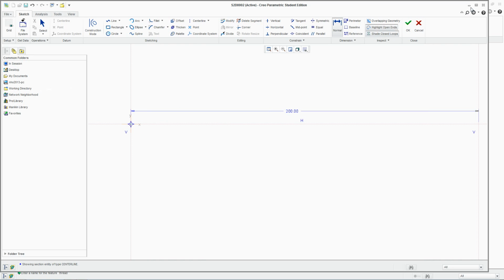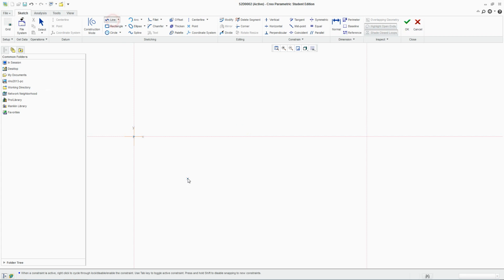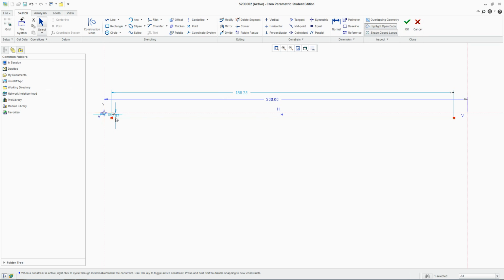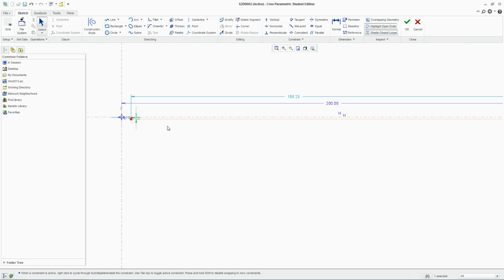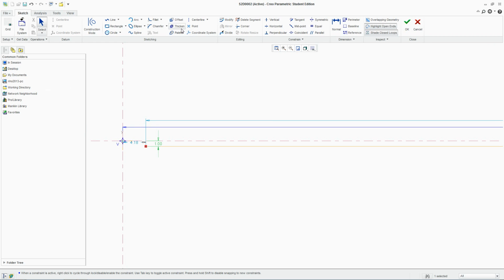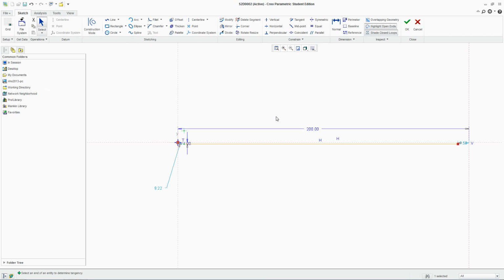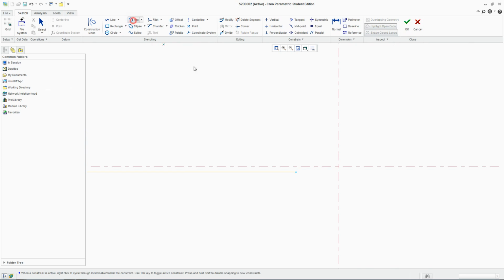Alright, so the tricky bit here, we're gonna draw a line. The cross section will sweep along without any changes until later on at the end. We'll make that 1 from the line here. The graph basically defines how the profile will move up and down based on where we want it to specify. I'll talk about that a bit more, but just go to arc and draw the arc. Make sure it's tangent with the line, and we'll do that again over here.